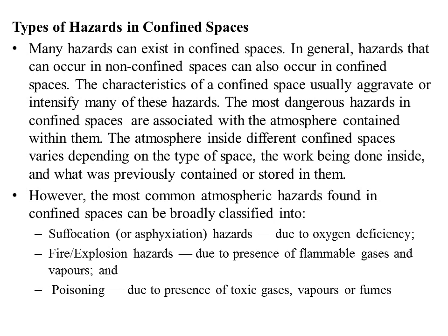Next hazard may be fire and explosion hazards. Because the space is confined, if any flammable gases or flammable material is there, it may catch fire. Then poisoning, because in a confined space the movement of air is very difficult, and if any toxic gases or vapors are there, it may lead to poisoning of that person.